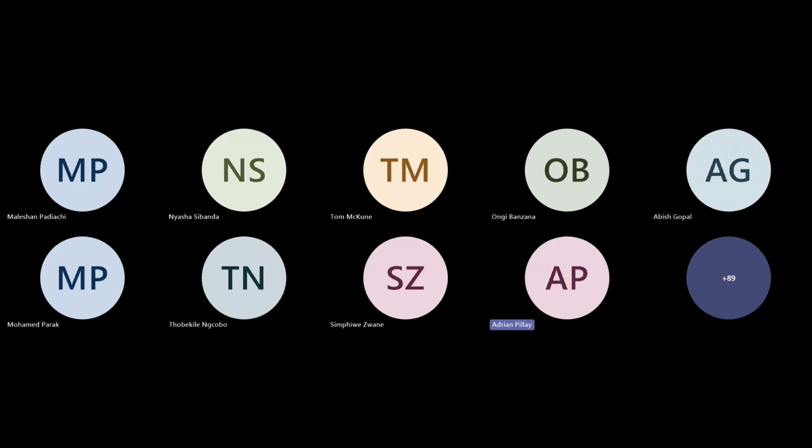Hi, Tom. Thank you. Hi, Lloyd, for your question. Adrian here. The substructure was in good condition. However, at the design stages, the cores were extracted to determine the strength and durability properties of the in-situ concrete. These were found to be within tolerances. Notwithstanding those tests, the existing designs catered for a railway live load, which was greatly reduced to now a mere pedestrian and pipe services load. I hope this answers your question, Lloyd. Yes, sure, it does. Thank you so much.